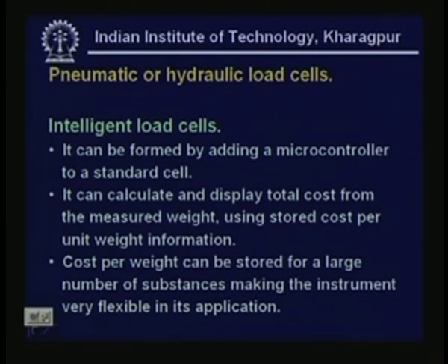We basically discussed two basic load cells, the link type as well as the cantilever beam type load cell. As I told you earlier, sometimes people call the link type a column type load cell, and the other is the cantilever beam type load cell. You will usually find that the cantilever beam type load cell is used for slightly lesser loads, whereas the column type load cells are usually used for larger loads.